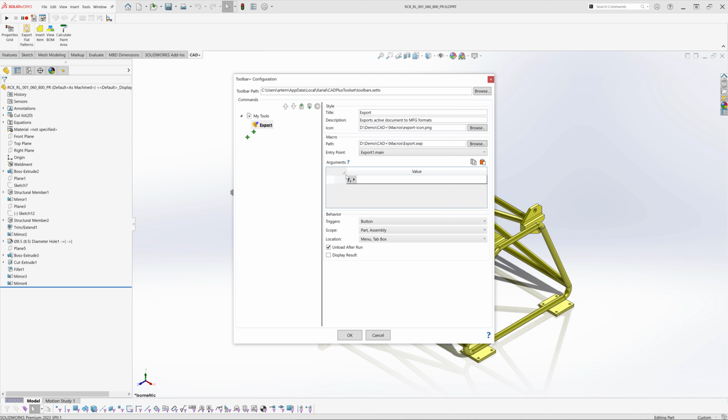One of the main limitations of VBA macros in SOLIDWORKS is an ability to pass user argument to the macro itself, which makes the macros hard to reuse, and you will have to create some user interface, pop-ups, message boxes, input boxes in order to collect input for the macro, or instead you can just use a constant in the macro.